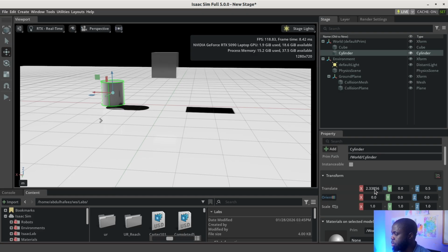One thing to take note of is if you just click on this without pressing Control, it's not going to allow you to do that. So you need to press Ctrl and left click, and then you can edit it. Also, without selecting, you can take your mouse to this text box and just use it to move, and once you move your mouse, it is going to change like that. So if you really want to edit it, you need to press Ctrl left click. Same thing for the Y. You can move it like that.